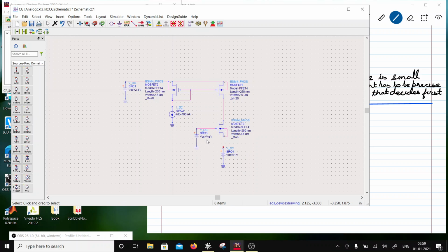And if it is 0.612, I'm going to say 0.71, or 0.75. So I have a 30 millivolt swing, for example, on the input. So 15 millivolts on the input side, on the lower side. So I would have the quiescent voltage at least 15 millivolts above. So it was 0.612, but let's say I'm going to do 0.71. Okay, so let's set that.